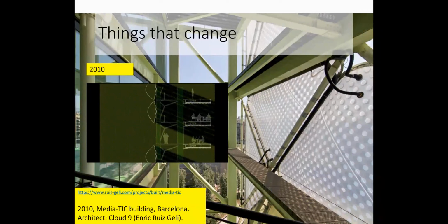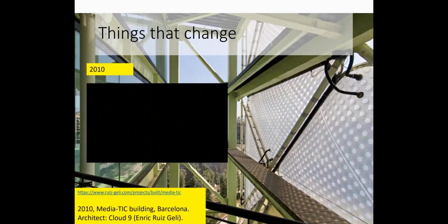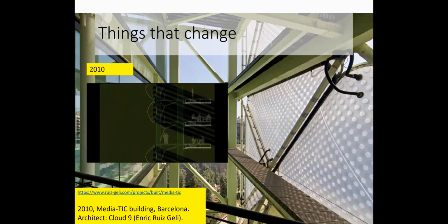It uses these ETFE pillows, which you can see on the right in the facade, as a shading system for the daylight. It has a triple layer construction where the central layer can move due to different air pressures in the chambers. And both layers have a fritting on their surface. So when you move the central layer towards the interior layer, the frittings cover each other. And in that way, you can decrease the opacity of the facade.